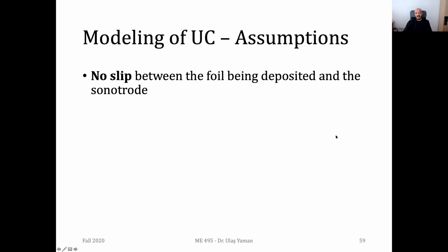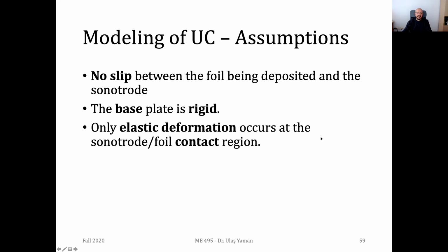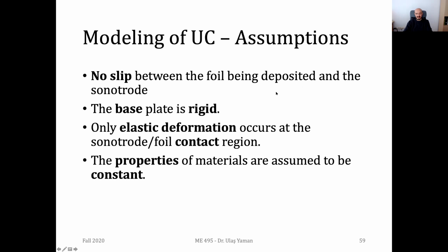We are assuming that, first of all, there is no slip between the foil which is being deposited and the sonotrode. So we are properly depositing the material. The assumption is that the base plate is rigid, it's not moving, it's always stationary. Another assumption is that we only have elastic deformation at the interface of our sonotrode and the foil which is being deposited.